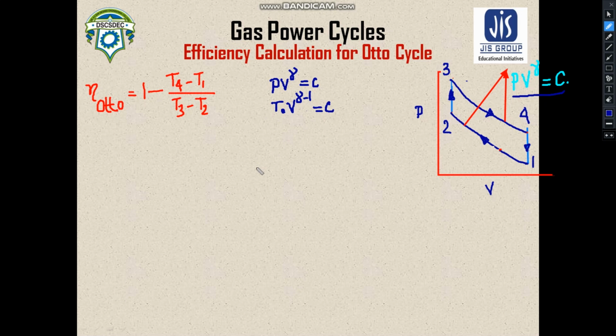Since any automobile engine is designed on the basis of the maximum and minimum volume of the cylinders, the relationship between the maximum and minimum volume which a cylinder can possess should be an important parameter. So the ratio between the maximum volume and the minimum volume is defined as the compression ratio.